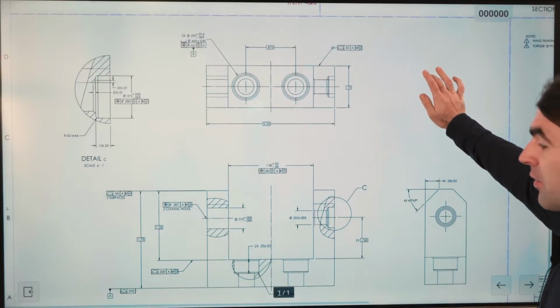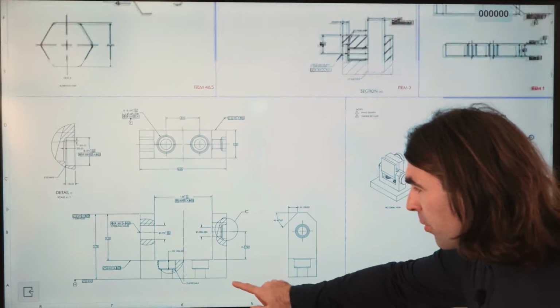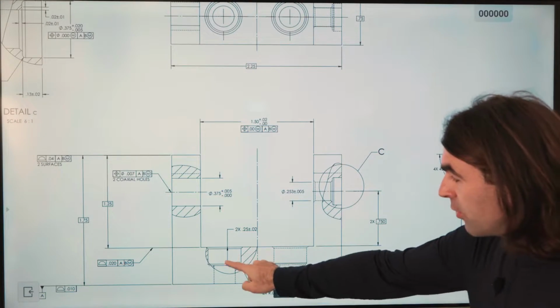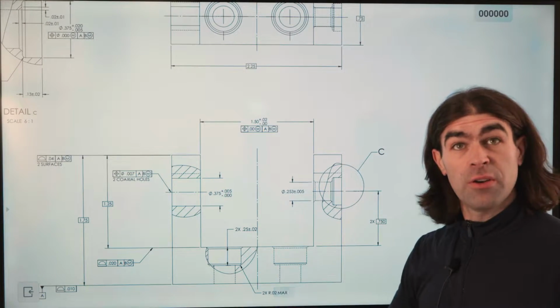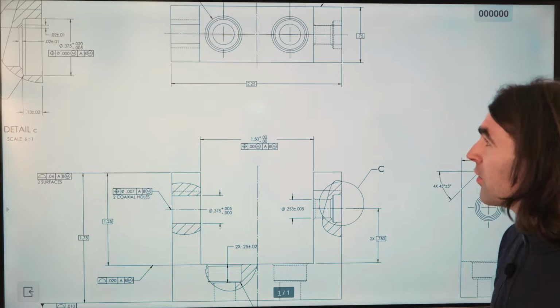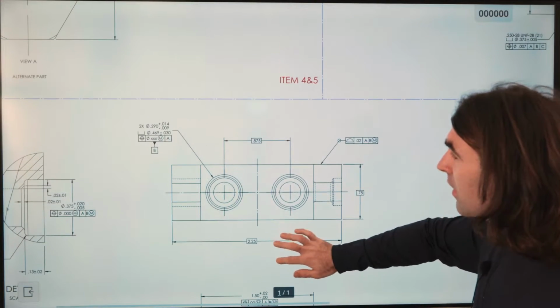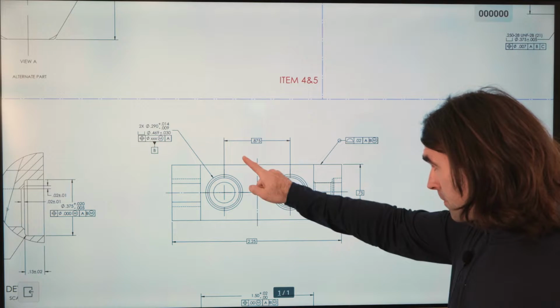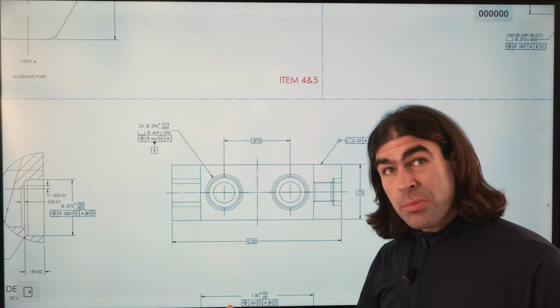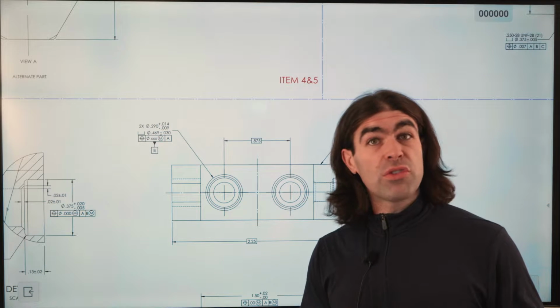So the part that gets mated up, you can see here are our counterbores. Our counterbores for our clearance holes, right? And then this extra area right here is our clearance hole. They're dimensioned up here from the top. So we've got our one basic dimension. And then the same idea with this part. The datum are those two holes.